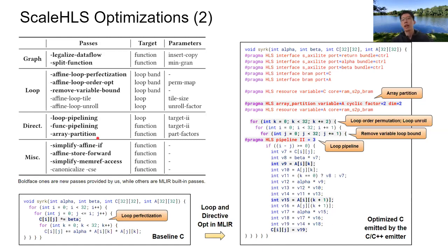This is because in this example, after the loop is unrolled, you can observe there will be 2 simultaneous array access operations in the loop body, which require enough on-chip memory bandwidth to achieve the expected parallelism.